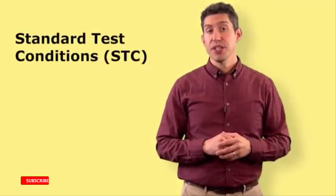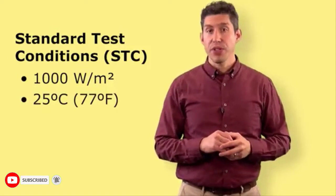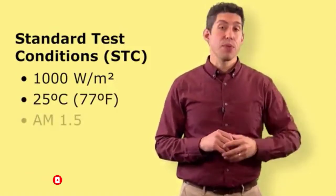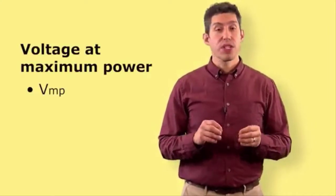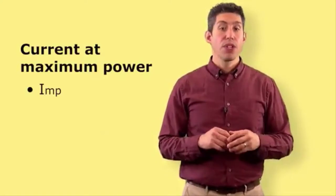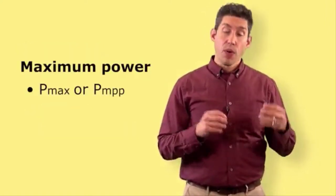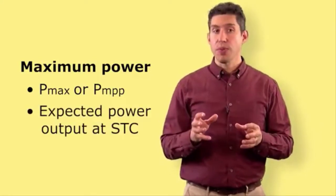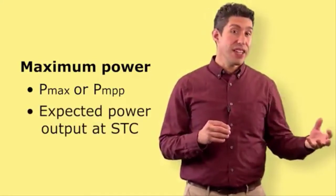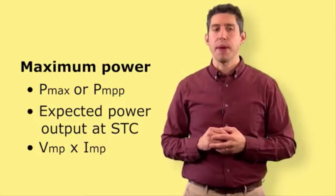Those terms are always measured under standard test conditions, again, which is 1,000 watts per square meter, 25 degrees Celsius air temperature, and AM 1.5 sunlight. The 5 terms are the voltage at maximum power, which is the voltage being put out by the solar panel, the current at maximum power, which is the current that's being put out under maximum power, and the maximum power, which is the power of the solar panel, which is actually a calculation of the voltage at maximum power multiplied by the current at maximum power.